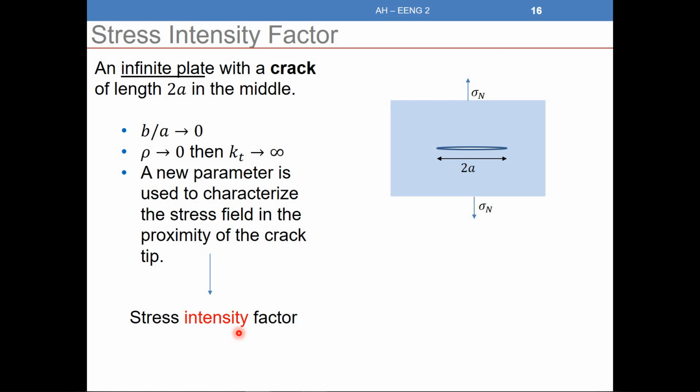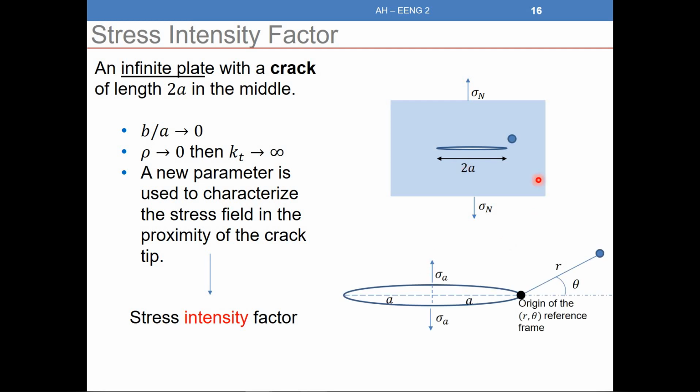Before, we defined the stress concentration factor when you have a stress concentration due to a discontinuity in the plate. In the case of a crack like this, a longitudinal crack, we define what we call a stress intensity factor. What's the objective of the stress intensity factor? Our objective is to find the stress distribution around the crack.